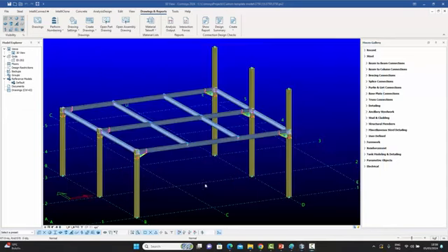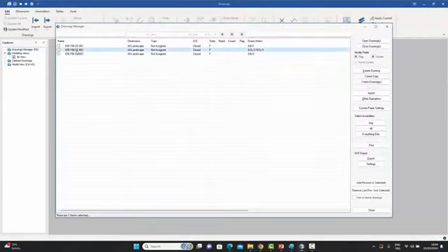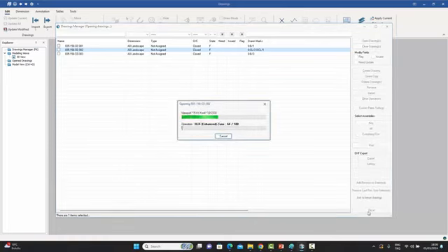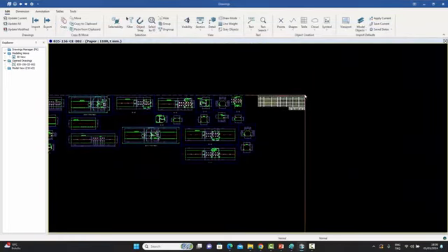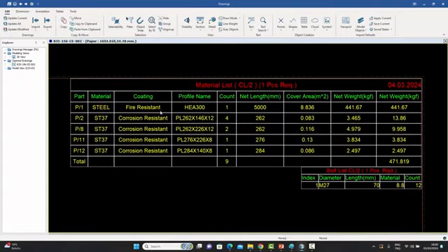And obviously, I'll just now quickly show you that these tables which you have created, these custom templates, can also be used from the layout manager. And I'll just show you the results. For example, I have a few drawings. If I open this drawing, you can see that this table has been created from the custom template editor. And over here, you have this user-defined field as well. So just to give you an idea, it's a very similar looking table.